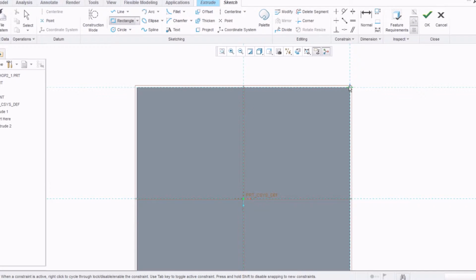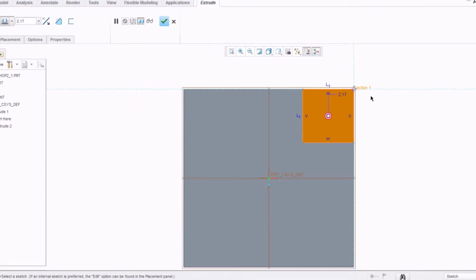So now, if we go ahead and make that corner rectangle again, you can see we can actually grab the corner, which is exactly what we'd like to do. So, left click, drag that out. Again, try and grab that length relationship to make everything equal, since we have the same size on either corner, and center click once. Drag that dimension up. This distance is going to be 2.5. You can also double click it and type 5 minus 3.5. Excuse me, 1.5. Sorry, not 2.5. 1.5. Same idea. Really useful tool. And click OK.